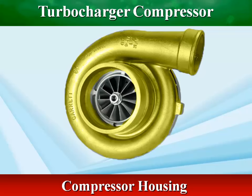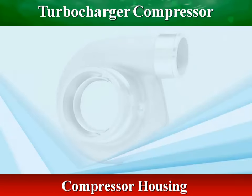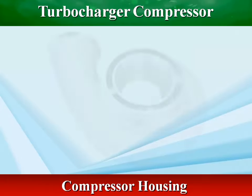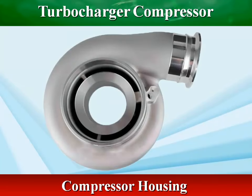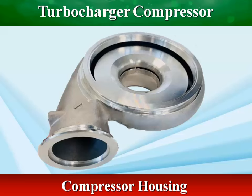The compressor housing, like the compressor wheel, is typically made from an aluminum alloy. The housing is the shell that encloses the compressor wheel. The spiral shape of the compressor housing gathers the high-velocity air and channels it toward the engine's intake. The compressor housing is designed to convert the high-velocity, low-pressure air stream into a high-pressure, low-velocity air stream through a process called diffusion.